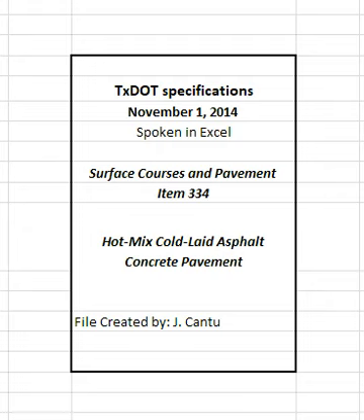The engineer may allow alternate methods for determining the asphalt content and aggregate gradation if the aggregate mineralogy is such that TxDOT 236F does not yield reliable results. Provide evidence to the engineer that results from TxDOT 236F are not reliable before an alternate method will be allowed. Use the applicable test procedure as directed if an alternate test method is allowed.